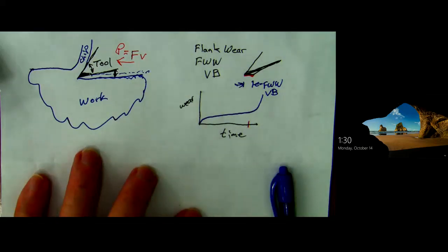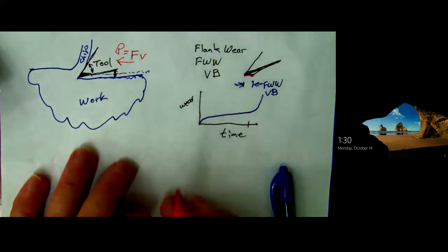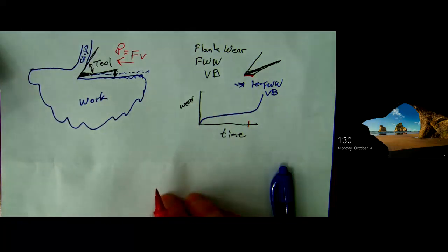No. So I'm not losing power on that. I have to watch the force. The force may cause my tool, depending on the exact nature of the cut and the shape of the tool, the angles, the edge to be rounded a little bit, whether it's pushing up or pulling down, probably pushing up in most cases. But there's no velocity, so there's no power loss.